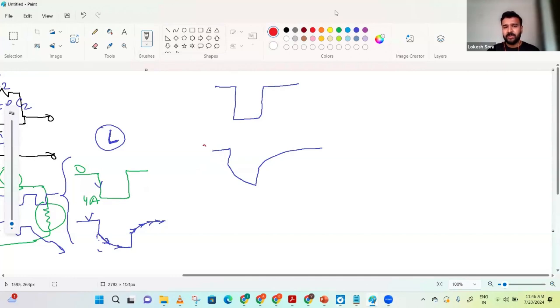When you see this sort of voltage behavior, this sudden drop, if you understand the circuit, this is coming from the series resistance. Similarly, when you take off the load from the circuit, there is again this sudden jump. So this is resistance into current behavior. This drop is because of the series resistance because it is an immediate drop. While this behavior, if I try to understand this dynamics, you would find there are two dynamics. One is a faster dynamics in this, and then another is a slower dynamics in this.